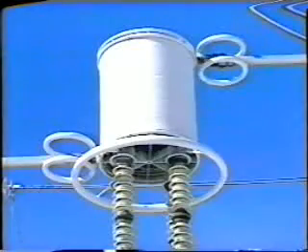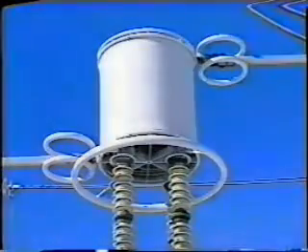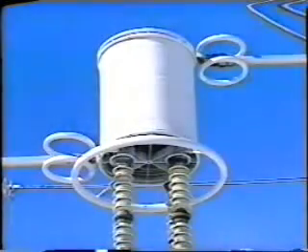Even in normal operation, the line trap runs quite hot due to the high current flow, and this can sometimes damage the tuning capacitors. If a capacitor does fail, the line trap will no longer be tuned to the selected carrier frequency, and this could cause misoperation in the event of a fault. Now, later in this tape, we'll see how to regularly check the carrier for signal power.